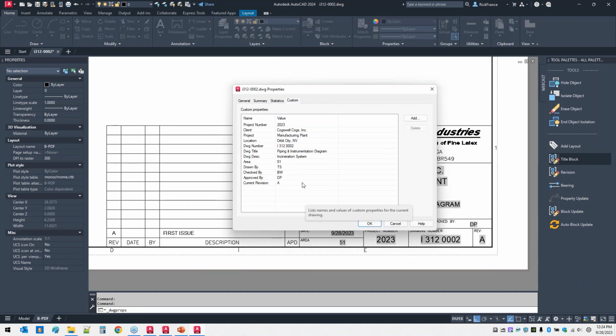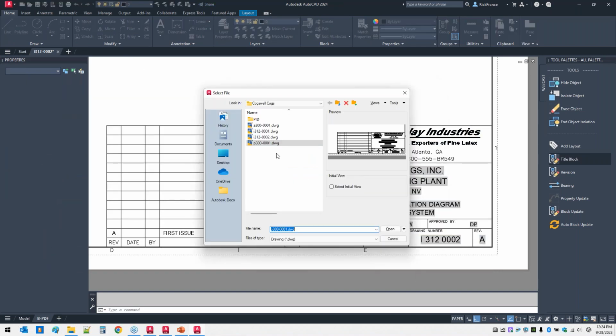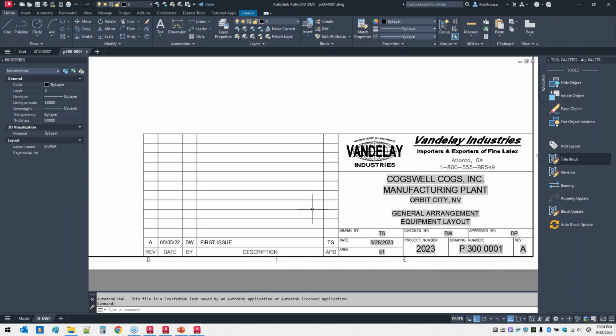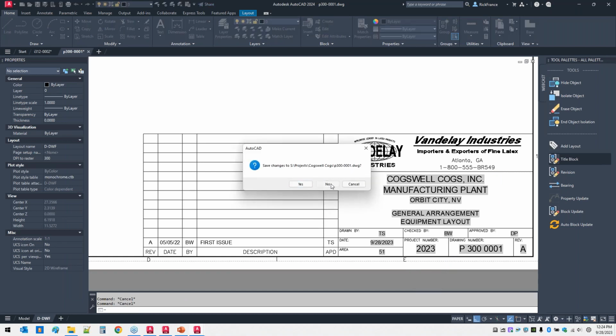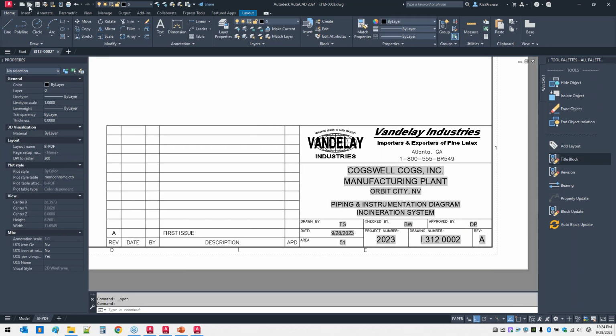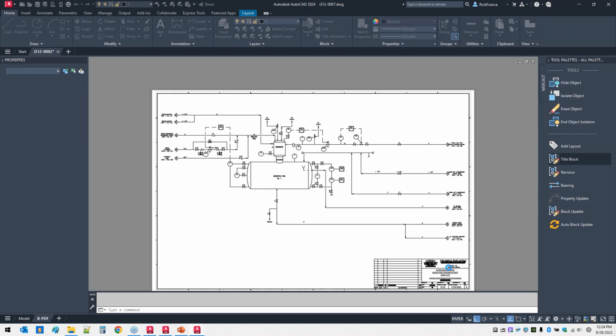And you'll see my title block opened up immediately because it updated the project's properties here that would be communicating with Vault. So it updated everything, but if I then go over here and open up this drawing, there you go. Same changes just happened, and I could open up any drawing in this folder and subfolder.